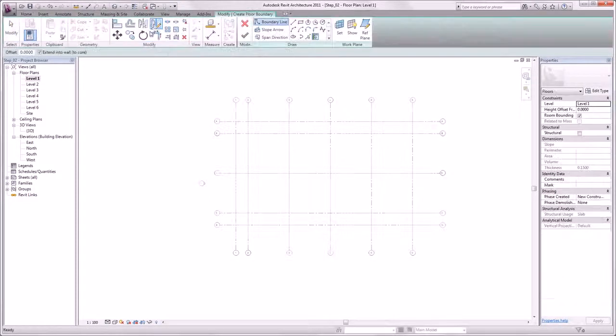Everything is gray. That shows us that we are now in a sketch mode where we can draw the boundaries of our element. We select the rectangle tool and we draw a rectangle from the right top corner to the left side. We see here 3 lock symbols, which give us the possibility to attach the boundaries of our element to the grid lines. We click the lock symbols.